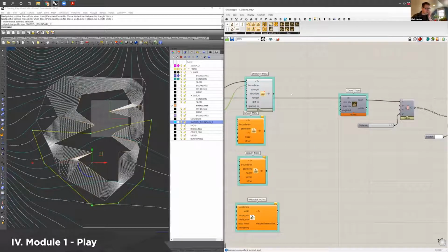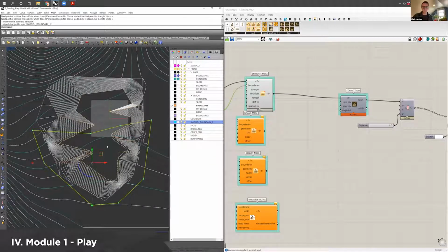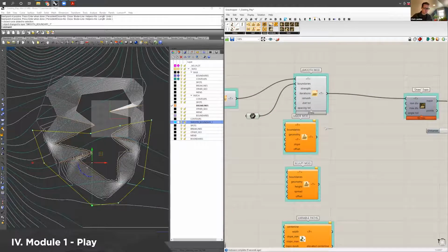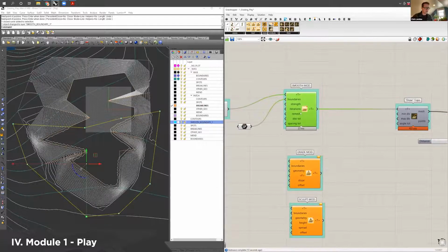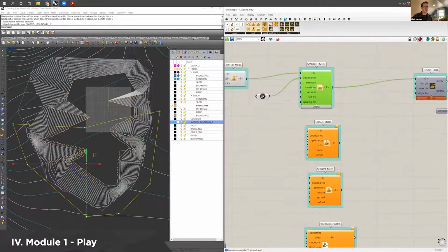And then the last step is to just make sure that I'm drawing this topo and not the other one. So we'll plug this in here. And boom, I have some smoothing happening just in this limited area. There's some things I can do to change that. If I want the smoothing to be more dramatic, there's a few ways to do it. One is to do more iterations or try to make, I mean, strength, it's already at a 1, which is as strong as it gets, really.